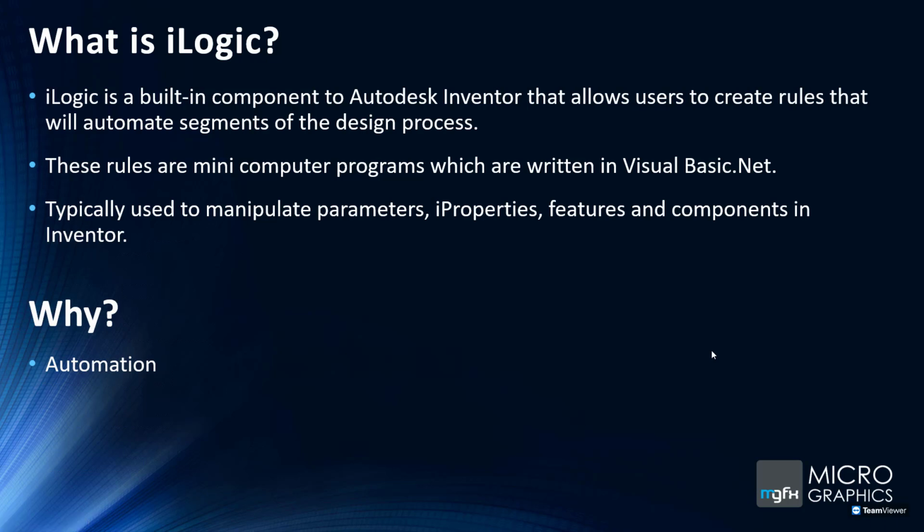Okay, so what is iLogic? iLogic is a built-in component of Autodesk Inventor that allows users to create rules that will automate segments of the design process. It's built in. It was introduced, I think, about 2012 as an add-in, and through the years it now comes bundled with Inventor. I'll show you where to find it when we open up Inventor in the demo, but it is sitting there. You do have it if you are on the latest Inventor, so it's ready for you to go. These little iLogic rules, as we call them, are just mini computer programs written in Visual Basic.NET.